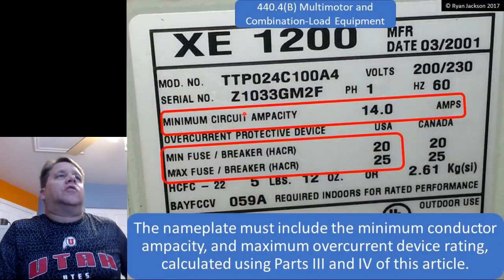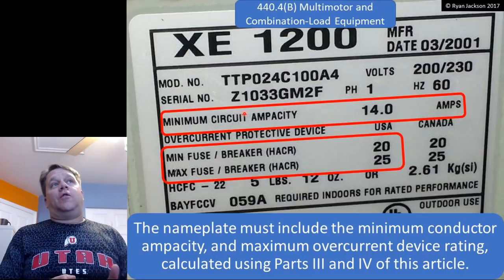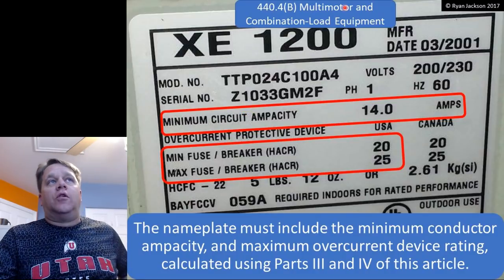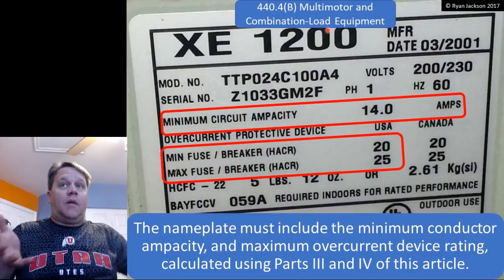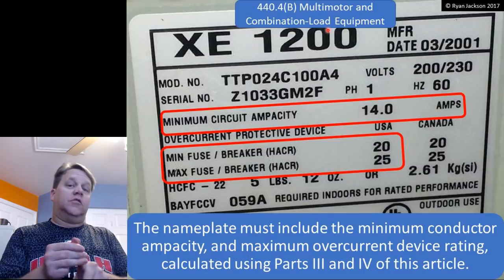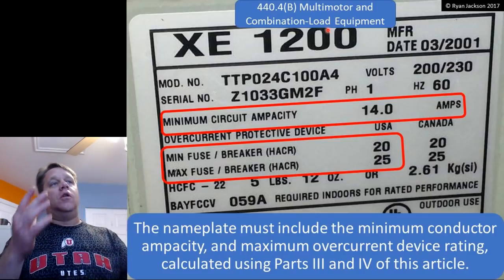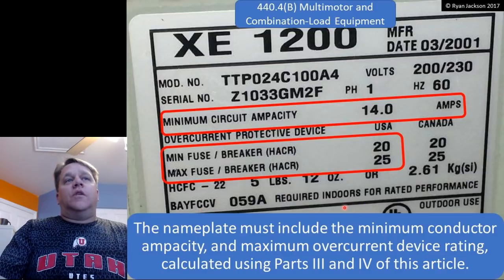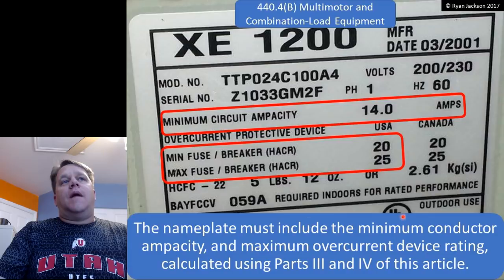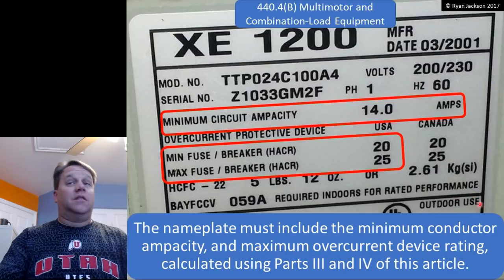Getting into the rules in Article 440. This is one of the best rules in the entire code. 440.4(B), multi-motor and combination load equipment. That's an air conditioner, right? It is a combination load. It has the hermetically sealed motor and it has the fan. So it's a combination load, Article 440. It says the nameplate must include the minimum conductor ampacity and the maximum overcurrent device rating calculated using parts 3 and 4 of Article 440.